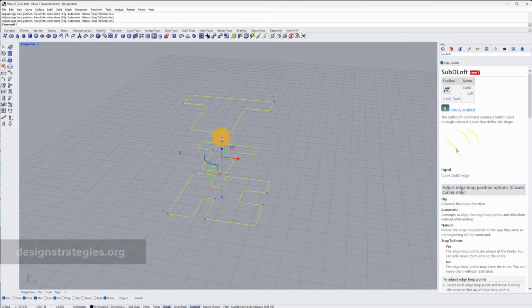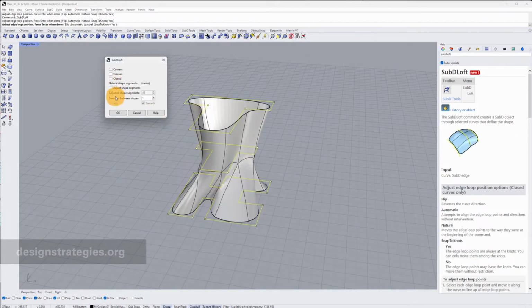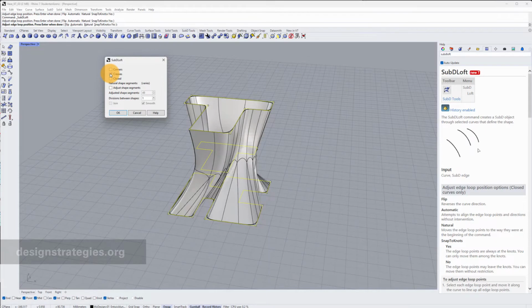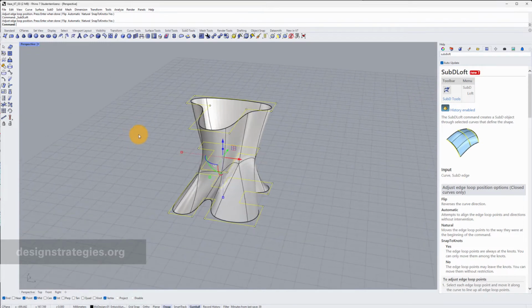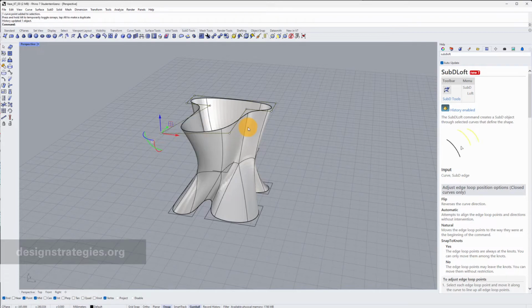If you want to get one step further in terms of the flexibility of your design, there's one really interesting feature called record history. If I activate this and go into my subdivision, and I just finish this really quickly, this looks good, with creases not important to me right now. Then you can take the control points and you're still able to change the design, and it just follows. This is possible because of your record history tool. So this is another good way of improving your design.